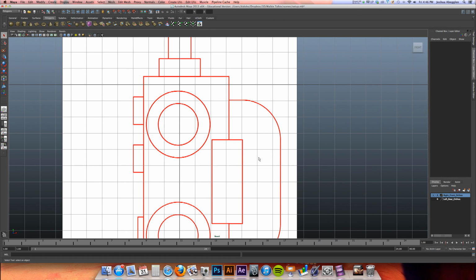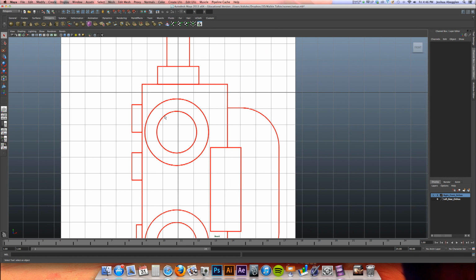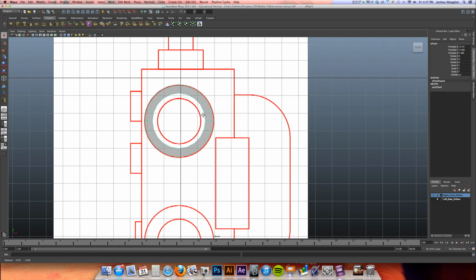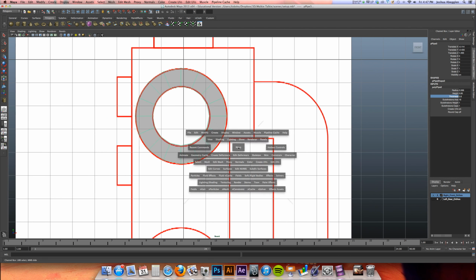All right, now when I'm modeling something like this, especially something that prominently features an ellipse, I like to go ahead and start with that as my base geometric object. Now, in this particular case, instead of a cylinder, let's go ahead and actually get started with a pipe. All right, so the pipe's created. I'll just go ahead and press return to commit that. Click on the polypipe input. I'm going to change my subdivision axis to 16. All right, I'm going to scale my thickness now. All right, and get that in place.